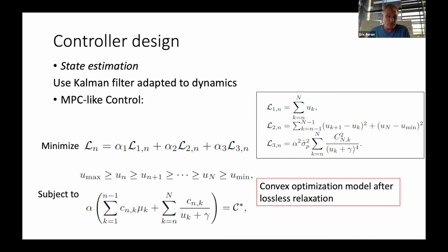However, what we do is we print only a small batch of the remaining layers, allowing ourselves to take yet another measurement afterwards and repeating the process, which gives us the opportunity to enjoy the benefit of feedback, which is continuous correction of what is being printed based on what is measured.